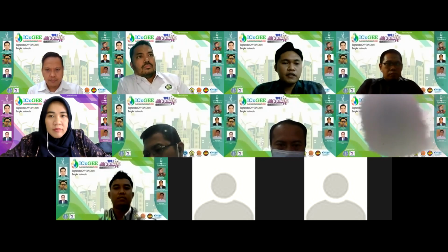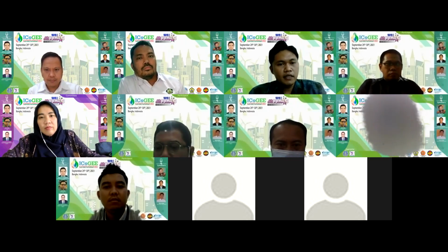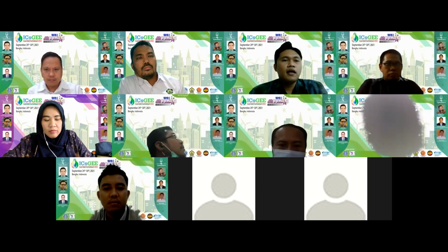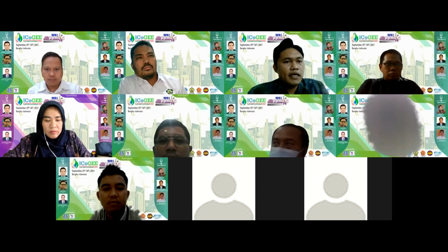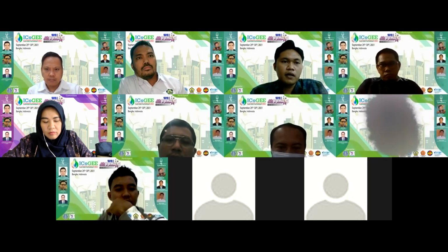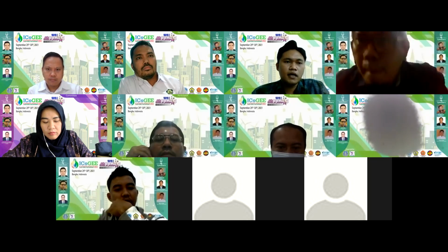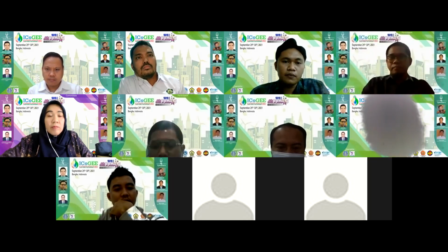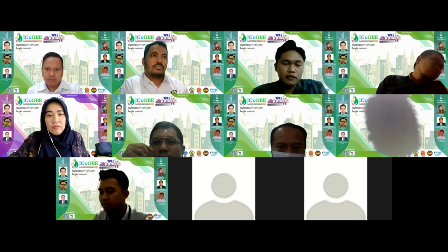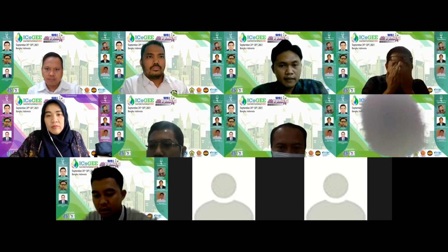After the heat is taken by the heat recovery steam generator system and so on, the flue gas itself needs to be treated by the air pollution control. For air pollution control, we can use a dry scrubber like we use in PLTSa Bantar Gebang to make sure that no dioxin and furan is released.